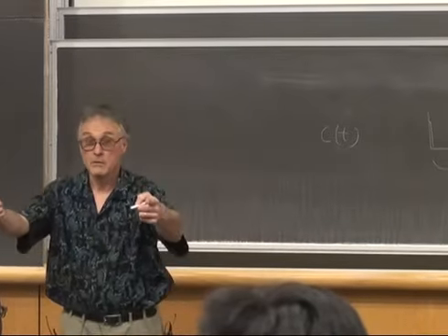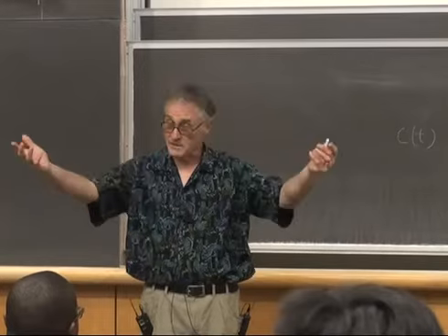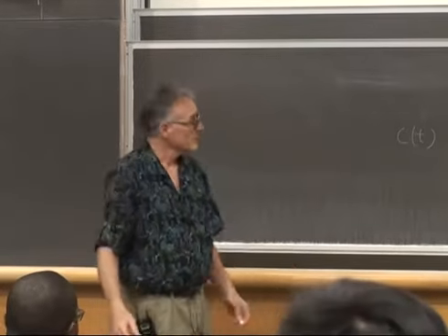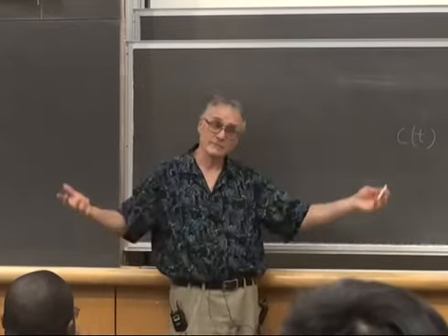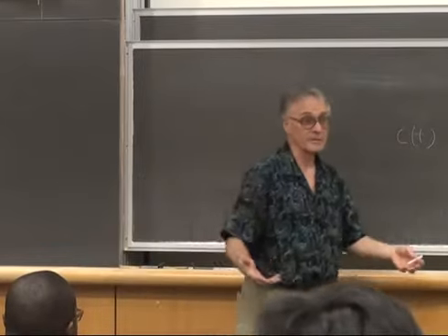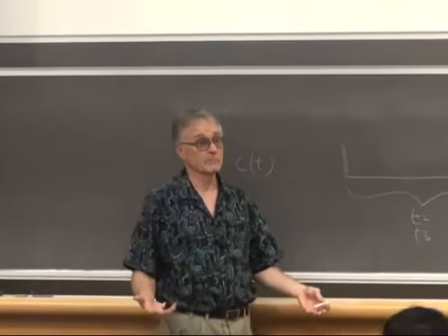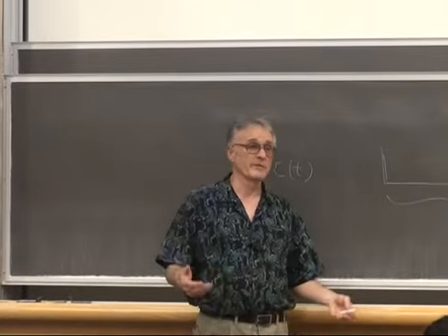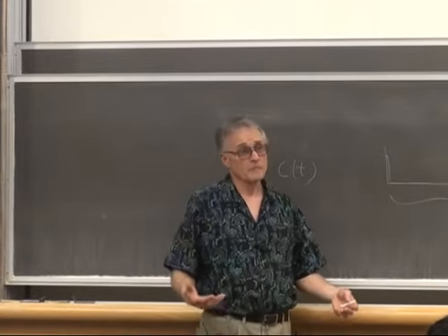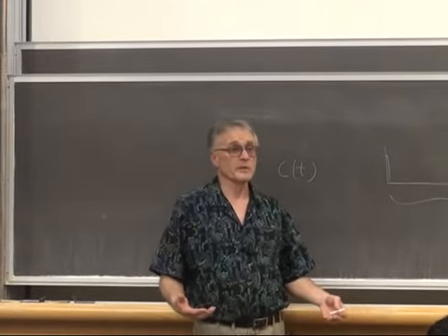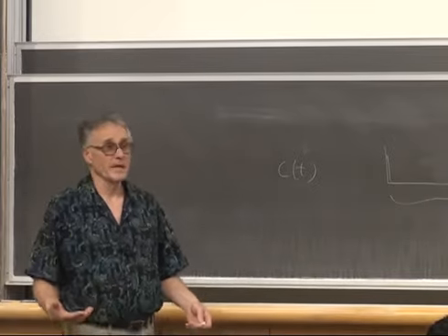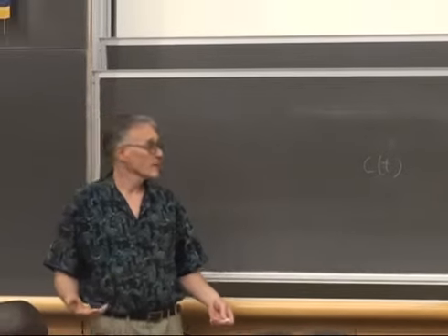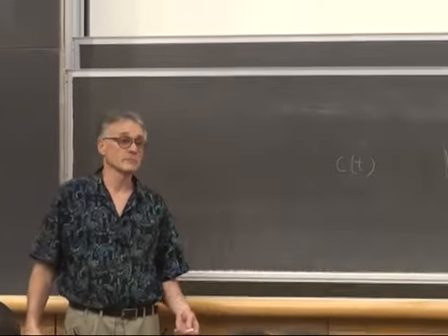Oh, come on. What's the maximum possible RPM error you can have? 3,000. You multiply that P times that, that's going to be approximately the maximum value of your function. There's going to be some derivative terms in there, but they're probably small. And some integral terms, but they're probably small. So let's say 90% of it is going to be P times the error. And so that's how you're going to scale it.